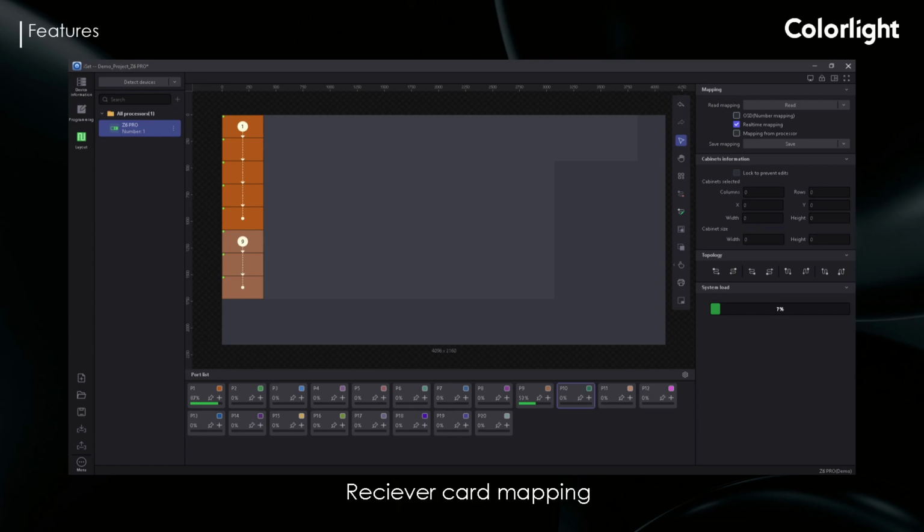So what that means is if you set this here and then you restart everything, power cycle the controller, it's going to go back to the previous setting that you had saved. If you want to save it and have it restore the same setup upon restarting, you have to click save. It's pretty simple. And when you first open this, usually what you want to do is just click read the mapping, and if there is one, you may need to change it.